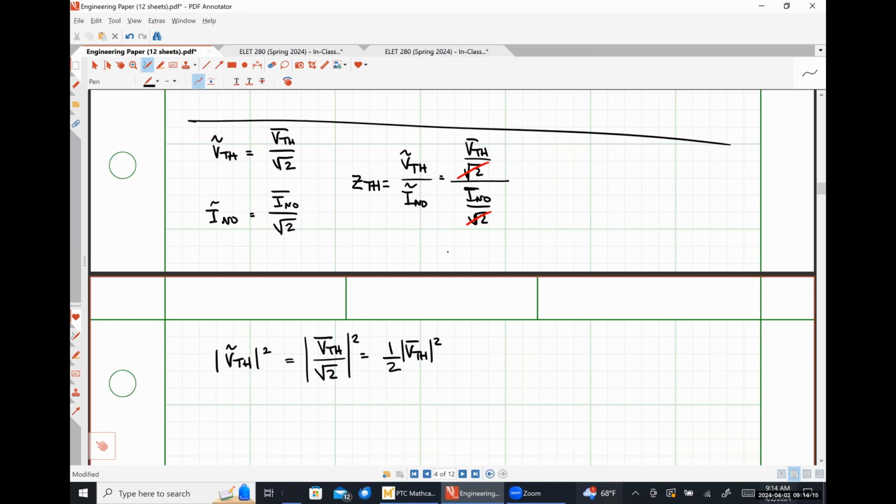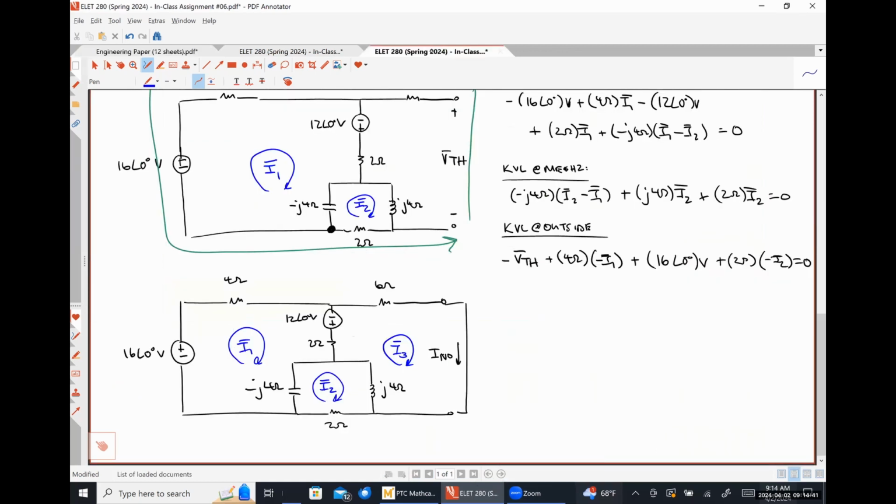All right. So anyway, long story short, realistically, you could just keep it as a phasor voltage and then multiply by 1/2 and you'll get the same result. Because you're just multiplying by 1 over the square root of 2 squared. So anyway, I have talked you through things. We've got about 30 minutes left, so let's review.